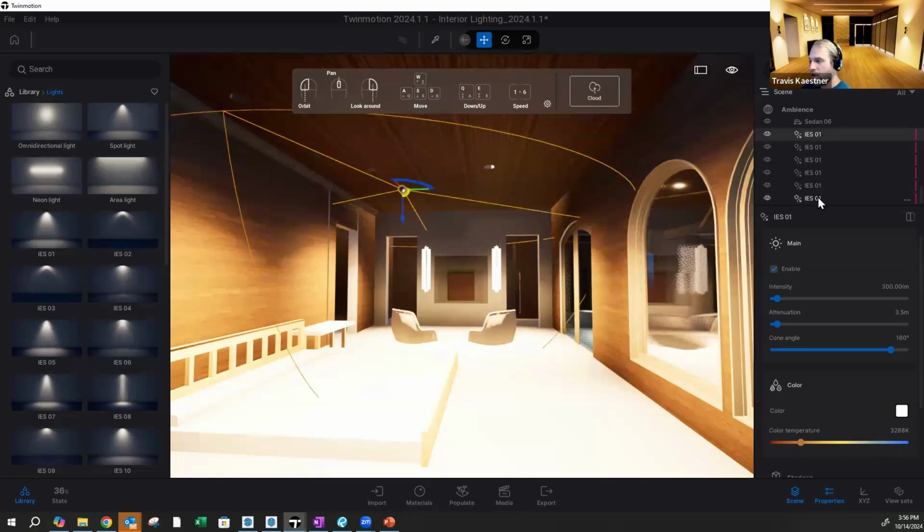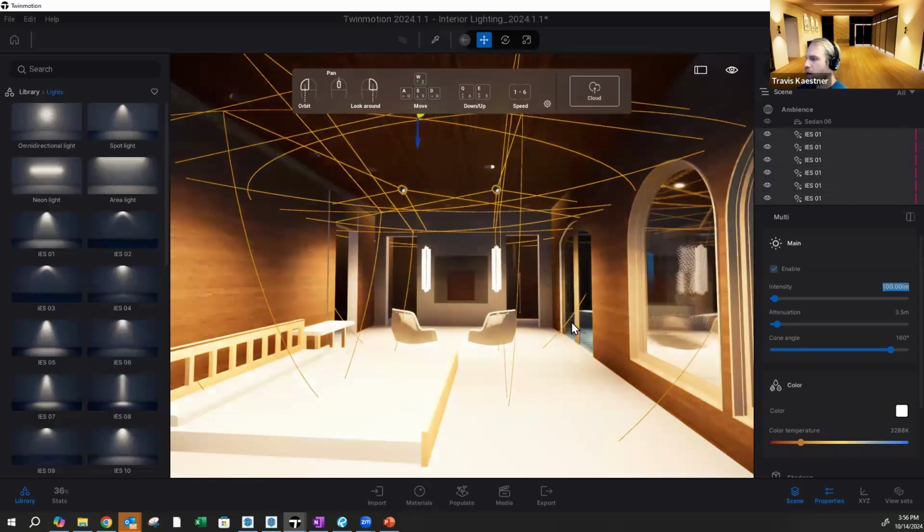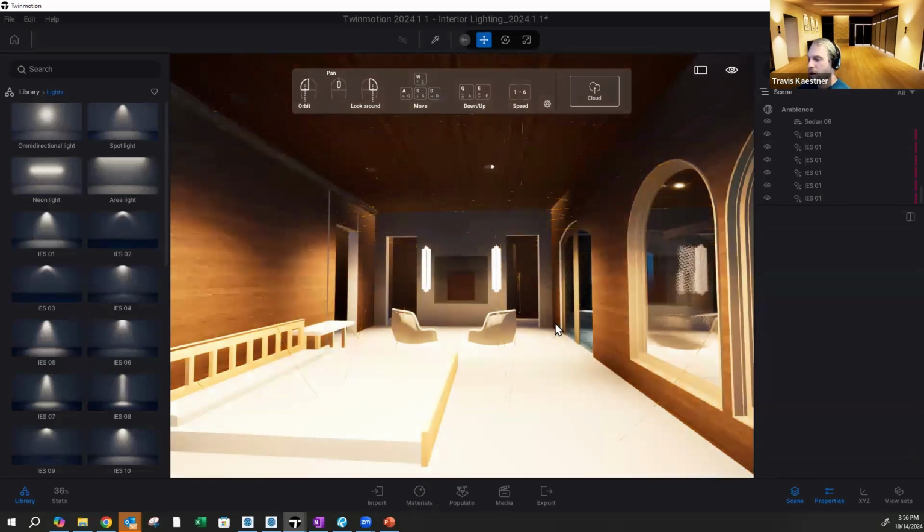It's important to know your finishes too, and that's also important for the amount of light, because darker finishes are going to absorb the light. It's going to take the amount of lumens that you're putting in there and make it not as powerful, because a lot of the light is getting absorbed by the material finish.